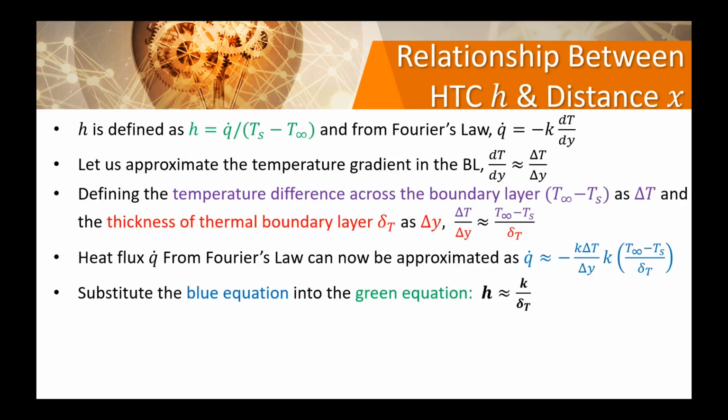Now, if you ask me, does H, the heat transfer coefficient, vary with the distance? The answer is yes, and in fact, significantly. It differs between a laminar flow and a turbulent flow. The rate of decay of H is also different.